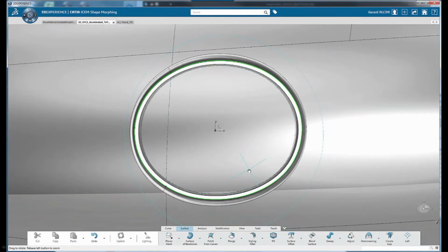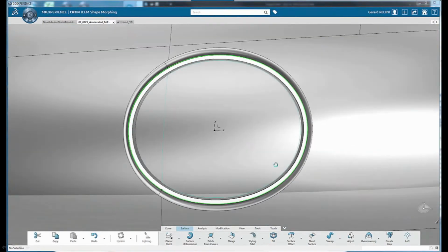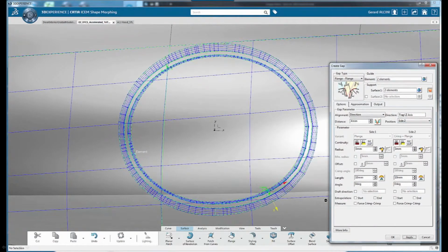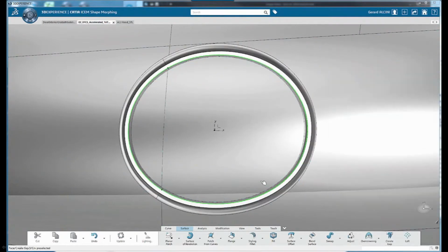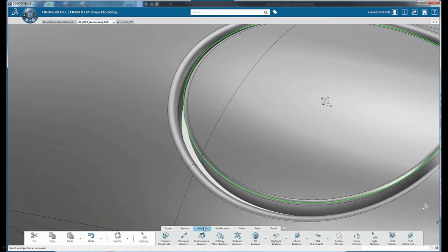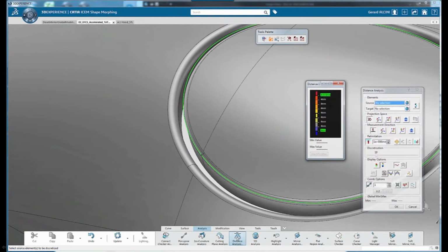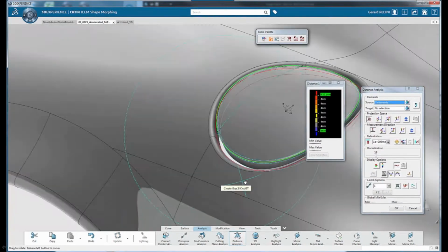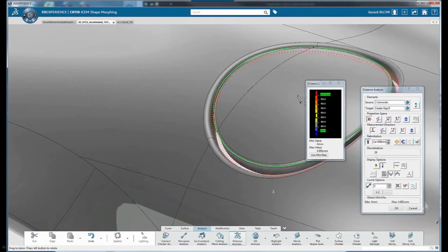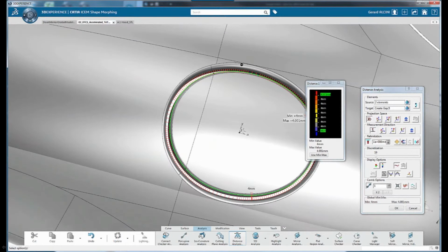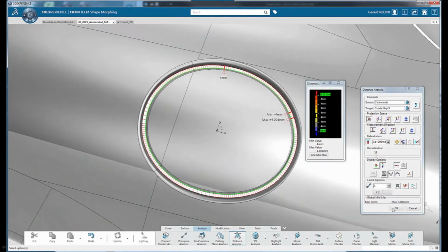So if you're given a cut line and the designer does not know which side that gap will be measured against, you always have the option to flip it to either the center, side 1 or side 2. And now we're just going to go ahead and put a dynamic distance analysis. Just double check and make sure that this gap is in fact the 4 millimeter gap as specified in the command. And as you can see, the minimum and max are dead nuts. It's 4 millimeters. Okay.